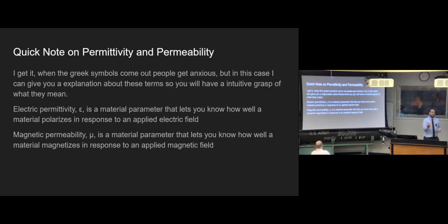When an applied magnetic field happens, you don't magnetize the same way. You resist it. You produce a magnetic field that is the opposite. So it's almost like you're shoving two norths together. But the material itself without a field is not magnetic at all. A good example of diamagnetic materials is just copper. Everyone's seen the example of dropping a magnet down a copper pipe. Everyone's also probably seen the example of taking a big block of copper and throwing a magnet at it or something. It will generate a field, now to be fair, that's Lenz's law, but it still applies because copper does have a less than 1 magnetic permeability, hence it is a diamagnetic material.